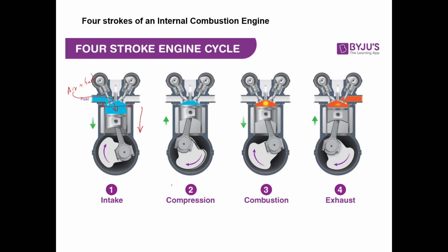Then you have the compression stroke. That means both valves are closed. In the previous stroke this one was open and this one closed; now this one is closed and this one is closed. Then your piston moves upward. You are compressing the mixture, which means you are increasing the pressure. When you compress, it increases the pressure. We call that the compression stroke.